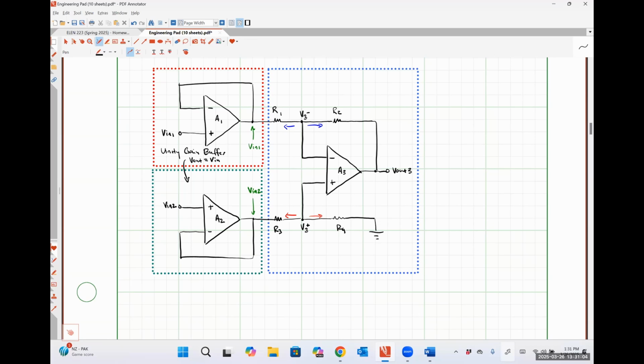So that's why this particular guy is used in applications where we're going to have incredibly small AC signals that we're trying to boost. It's going to actually wind up rejecting the DC signal because the DC signal is applied on both sides. So they're going to subtract from each other, and only the difference of the AC part is going to survive the amplification.